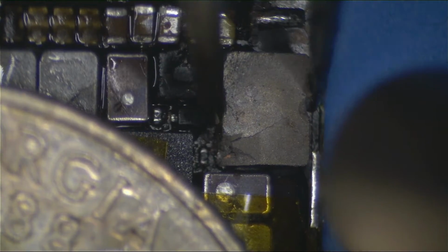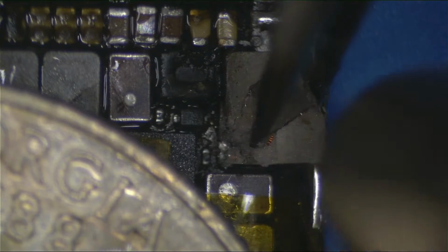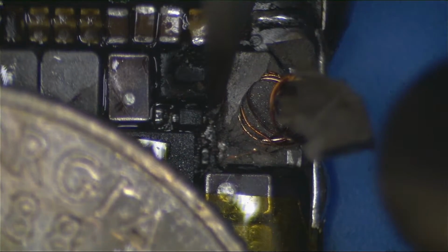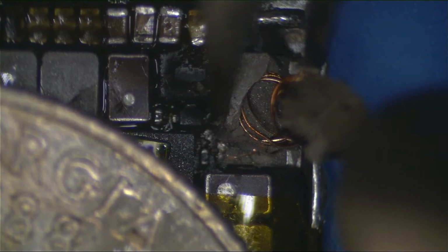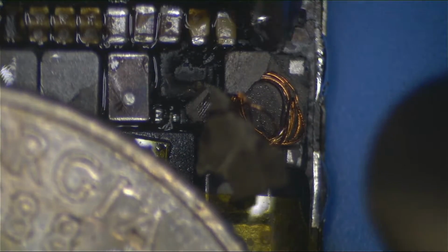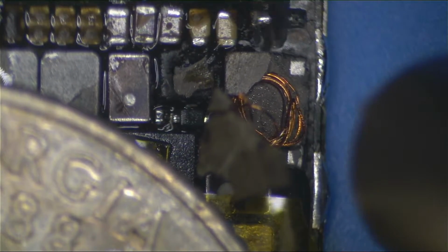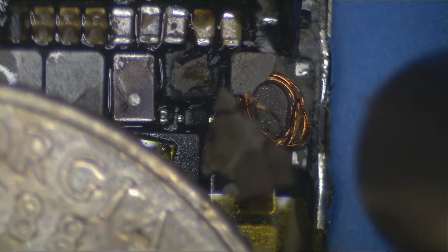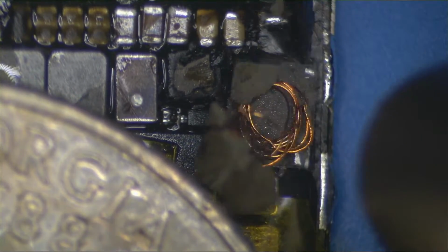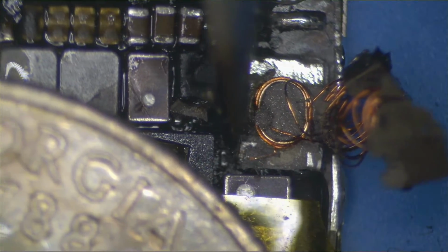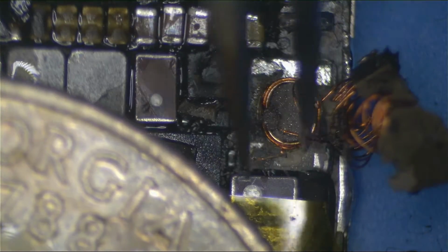Yeah, you can see it's already chipping away. You dumb motherfucker. Yep. Now there's the coil. That's what the coil looks like inside. And the trick here is when you start chipping it away like this, you can see when the pads are starting to melt, because you'll see the solder underneath turn shiny like that. And so now that's one side done. Now I just have to get the other side off.